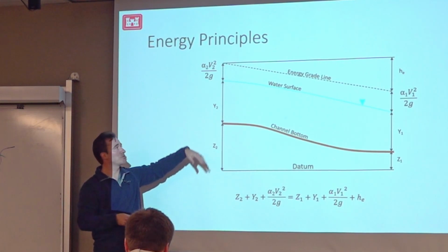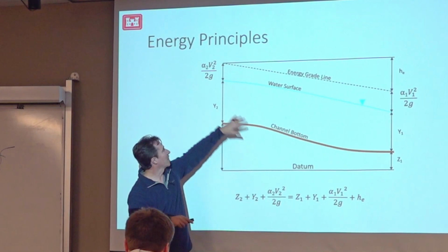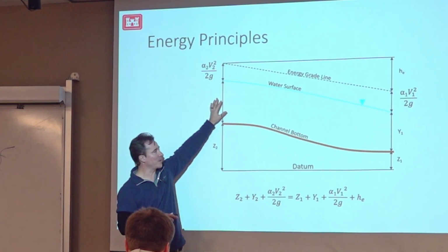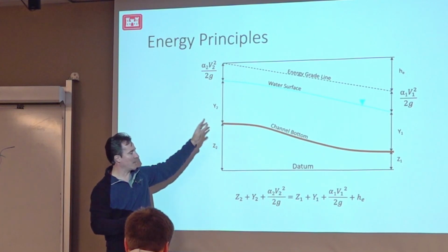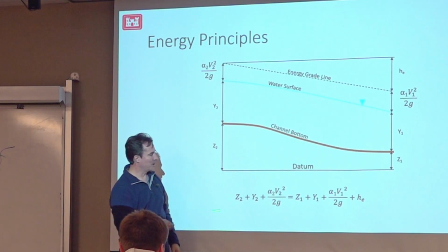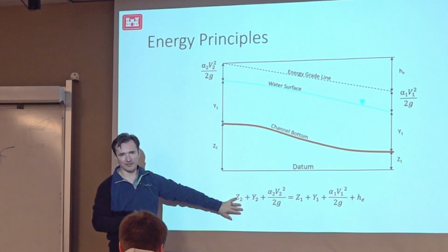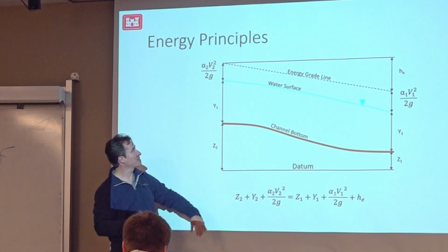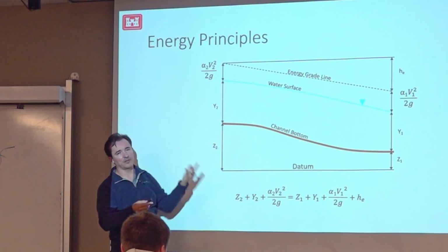The first thing you do is guess what it is based on this depth. You say, okay, I'm going to guess the depth is the same upstream, and compute conveyance and all of those things, then plug those values into my energy equation and compute a new water surface. And is this new water surface the same as the guessed one? If it's not, then it'll keep iterating.